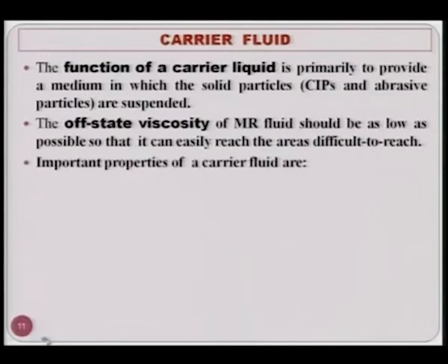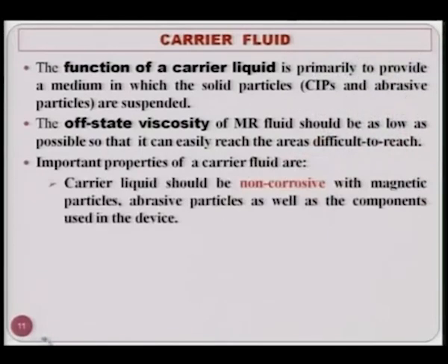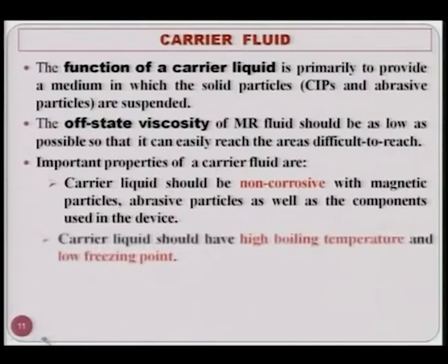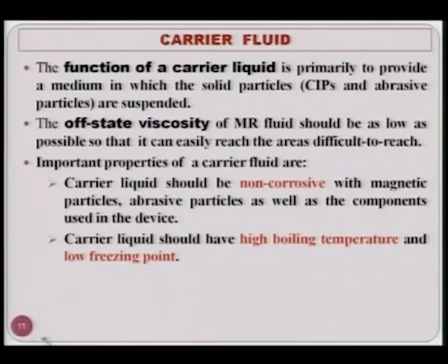Important properties of a carrier fluid are: the carrier fluid should be non-corrosive in nature with magnetic particles, abrasive particles as well as the components used in the device. Carrier liquid should have high boiling temperature and low freezing point.